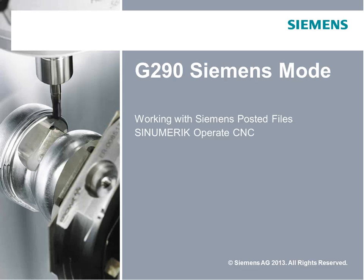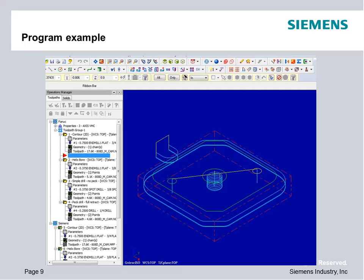When we get to handling the profile of the physical part, we're going to have it posted with cutter comp as a wear type of function. You'll see that a lot in CAM posted programs. What that means is the actual output cutter path is already compensating for the radius of the tool, but you're still going to see a G41 or G42 command turning cutter comp on, so you can still adjust the resulting cutter path. And there's some challenges when you get to working with systems like that. So we're going to talk about it, show you a few different tricks, and apply that through.